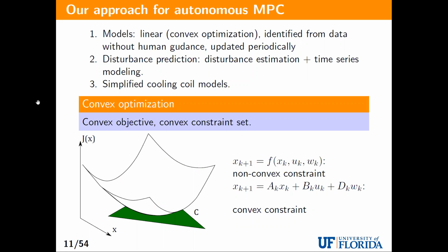So the approach that I'm trying to push in my group is, this is why the word autonomy appears in the title. I call it autonomous building, like autonomous vehicles, where everything has to happen by itself 24/7, 365 days a year. One of the problems with this modeling is that because HVAC models are so complicated, so much human expertise is needed to fit them. You can fit a model to your building and probably do a demonstration, but then 6 months later, the model is no longer accurate. So you have to go in and muck with the model again.